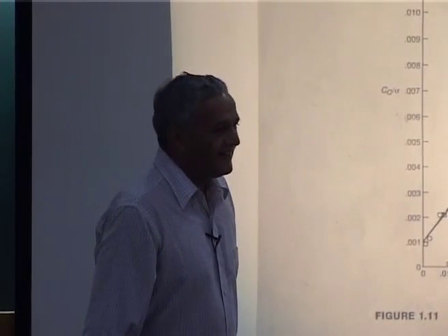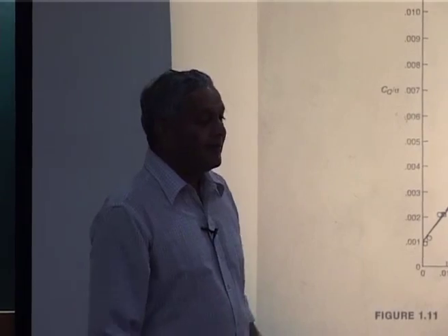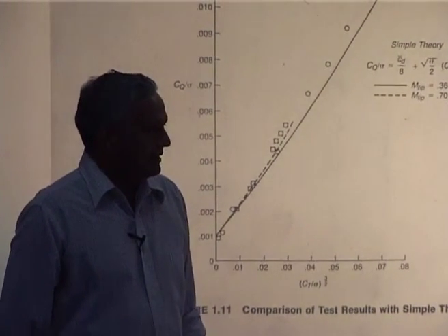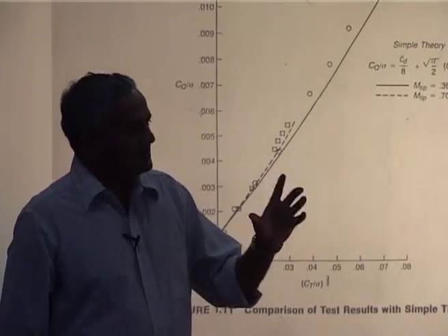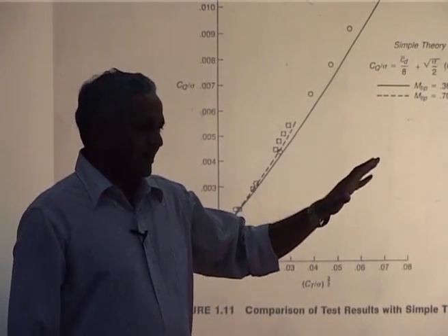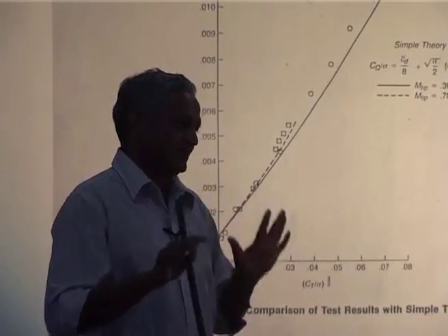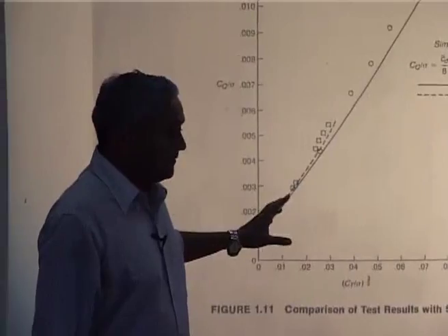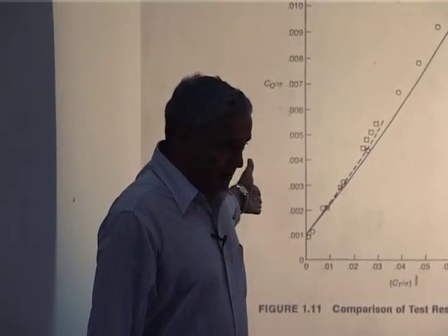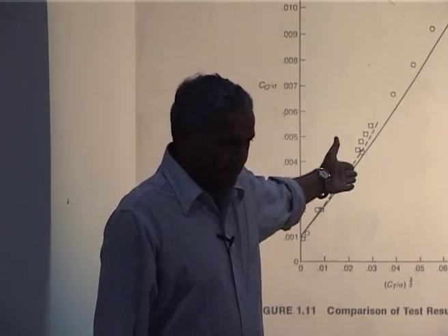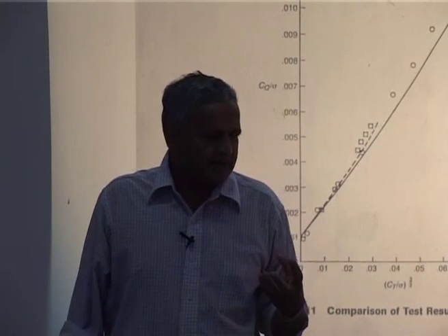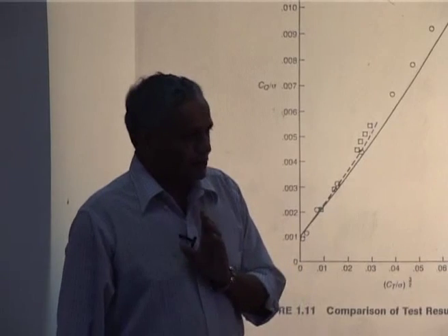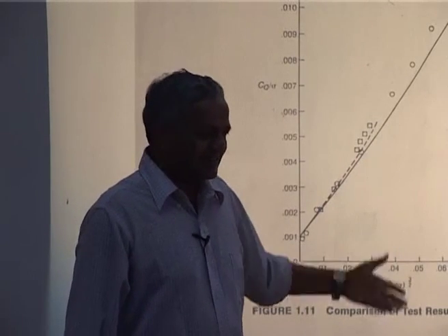Does this mean that we cannot compare helicopters with different solidity ratio? Usually you compare rotors of similar class. Rotor means similar weight class. But even then, we compare two helicopters with a different weight class. Figure of merit is not treated very seriously in actual design. Of course, if it is below 0.5 or so, it is a bad rotor.